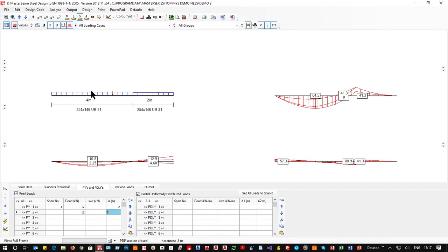So I've got these 2 point loads, and I can change the scale of both the UDLs, and I can also ask it to give me values, give me distances. Now we're getting the value up here including the density, so we're getting slightly higher values due to the self weight of the beam. If I turn off density, I'm back down to my net values